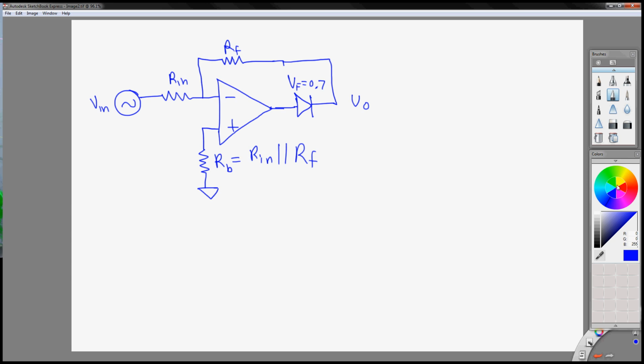So let's examine this circuit. Under what scenario will this circuit be active versus inactive? When this voltage is negative relative to the output, then this diode is in an inactive state. So the only time when this circuit will output Vout is when the current flows this way, and since this is 0 volts, there's a reference here, that suggests Vin has to be in a negative cycle for this circuit to be active.